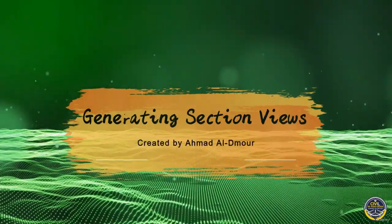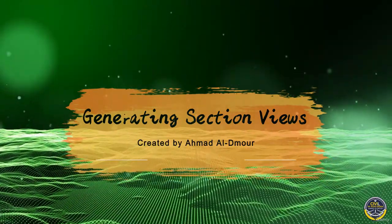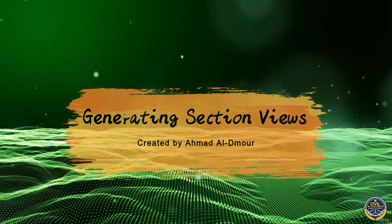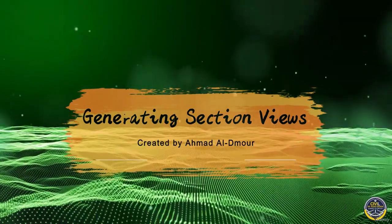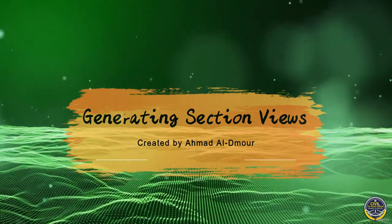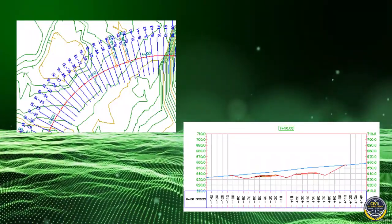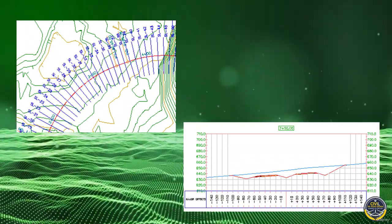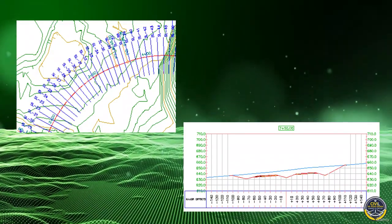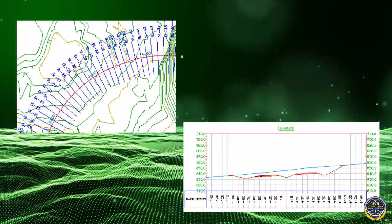Welcome back. In our previous lessons, we created a complete 3D corridor using an alignment, profile, and assembly. Now, it's time to move from a 3D model to the cross-sectional view of our design. In this lesson, we will generate section views from these sample lines, visualize the roadway components, and analyze how our design interacts with existing ground.